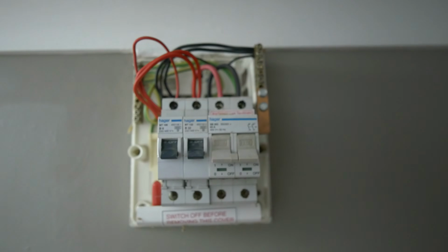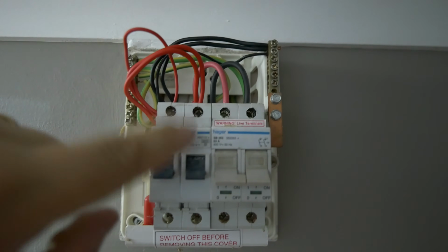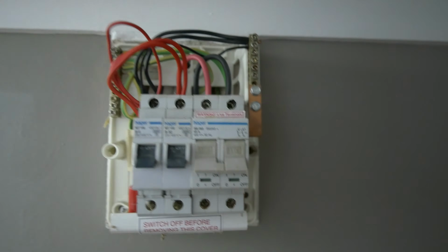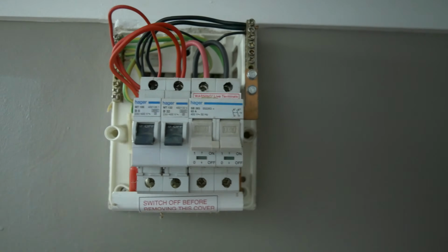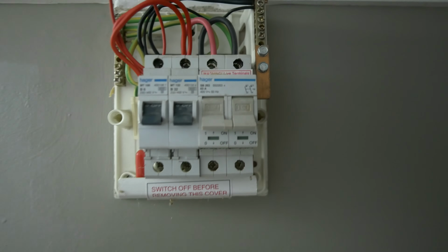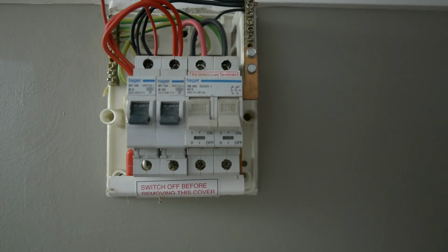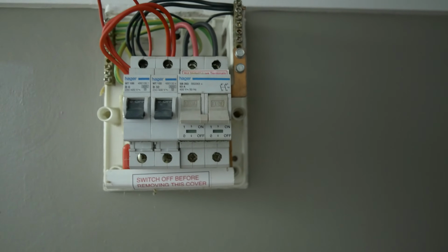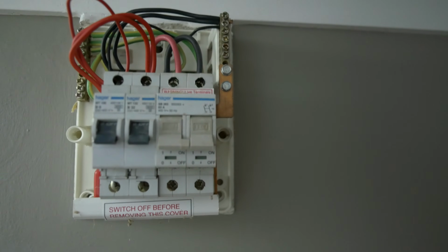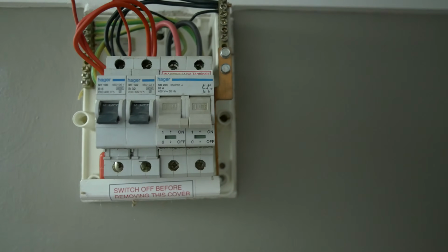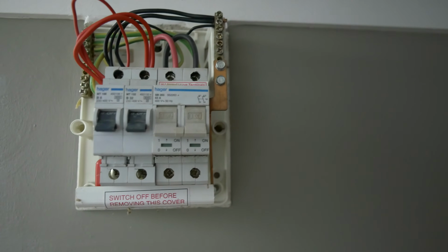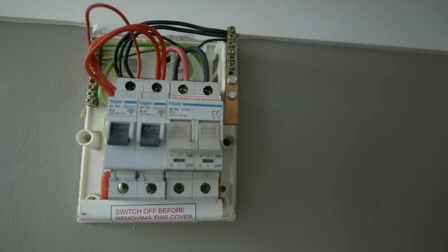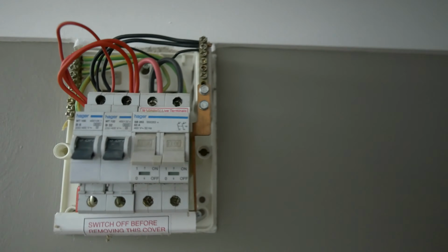So for the eagle-eyed among you, you may have noticed that I popped the ring neutral into the wrong MCB when I've been popping them back away to the lighting, and that's a firm example of why you need to double and triple check everything you're doing, because that's a simple mistake you can make when you're deconstructing a system, if you're not careful, especially in a busy board. So if you're taking terminations out, you're putting jumper leads in, before you're re-energizing the board, double and triple check everything you've done and interfered with visually so that you're happy it's hunky-dory to then reconnect and energize to do some of the live testing. And that was noted by me.